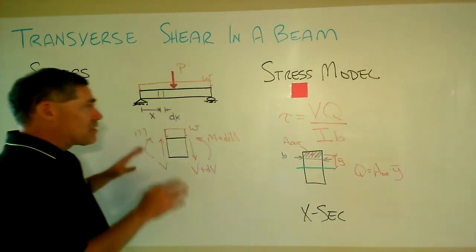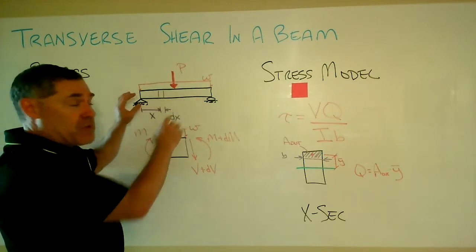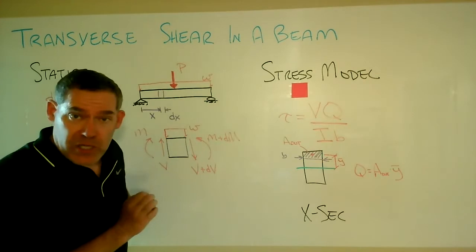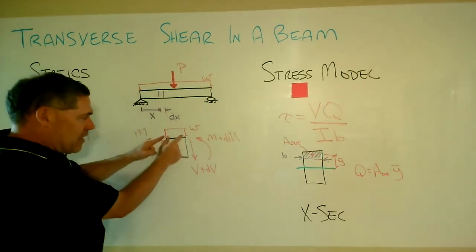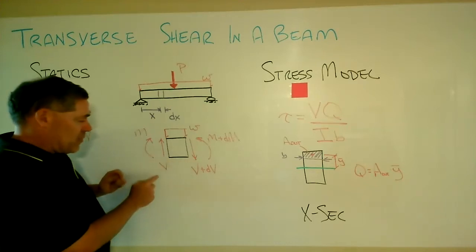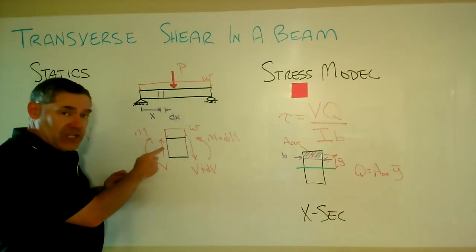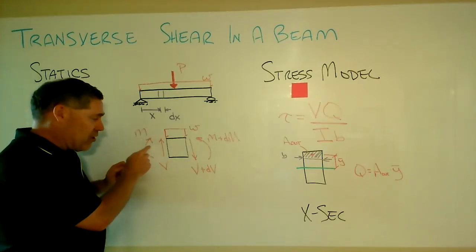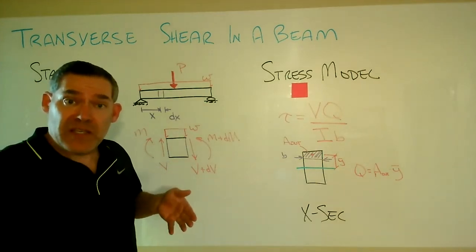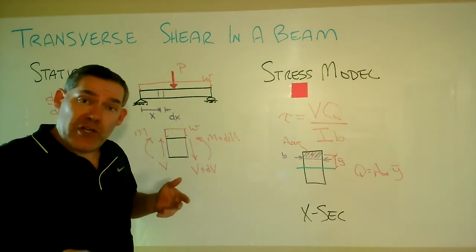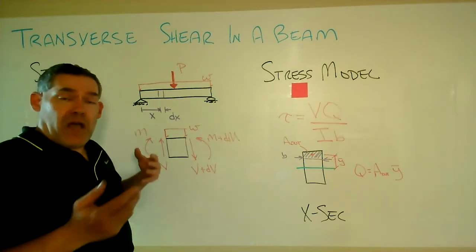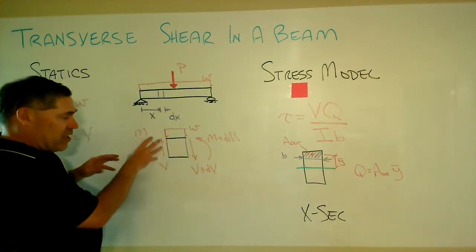We learned back in statics how to handle the situation when we had a variety of loads come in and take a little tiny differential element for the free body diagram. That's this thing expanded here, a little dx across there, and we learned about the sign convention for internal forces of the shear and the bending moment. What's shown here on the board, of course, is the American or US designer sign convention. The Europeans do it a little bit differently. There's positives and negatives for either one, but we'll focus on the American designer sign convention here.